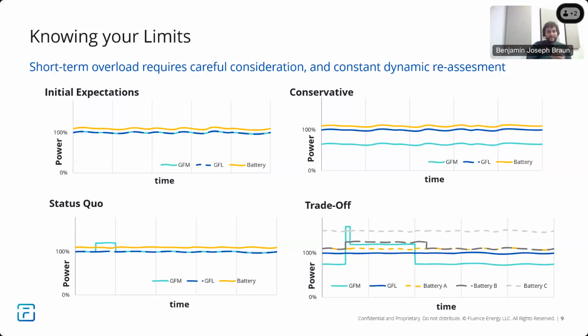So, not a concrete example, but if you overbuild by 10%, I can give you 50% overcurrent for a short time, versus if you don't overbuild, I can only give you 10%. So ultimately, economically, it starts to trade off, in particular for the transient services that grid forming controls provide.